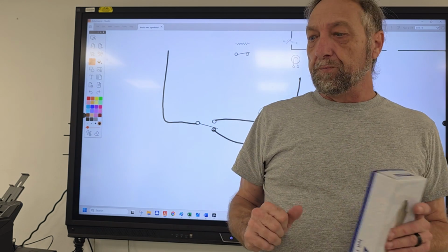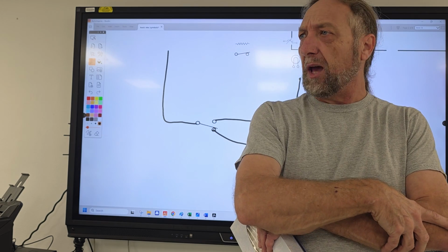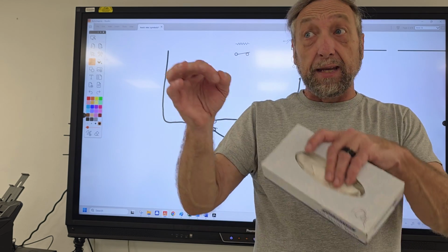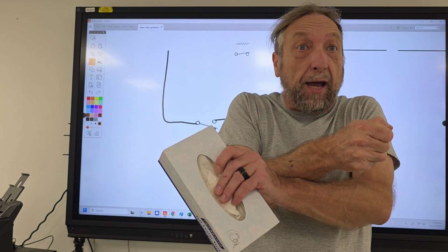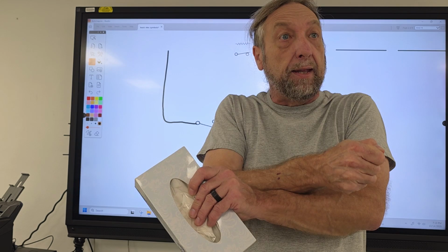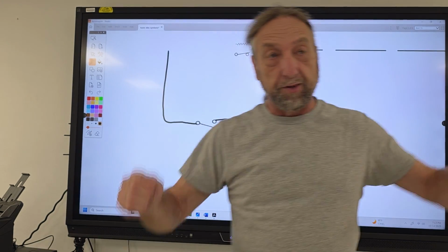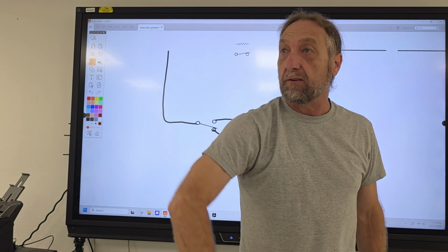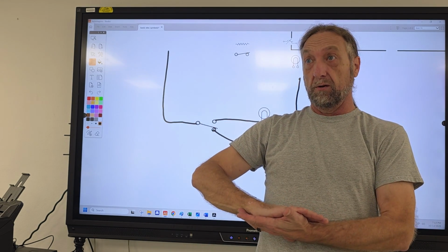So I said to myself, well, brand new stove, this thermostat blew up. Either something inside the oven is shorted, or maybe they put the wires on one of the switches wrong, and that caused a direct short. So I lift up the top. Right there inside, underneath the burners, is the diagram glued to the machine.